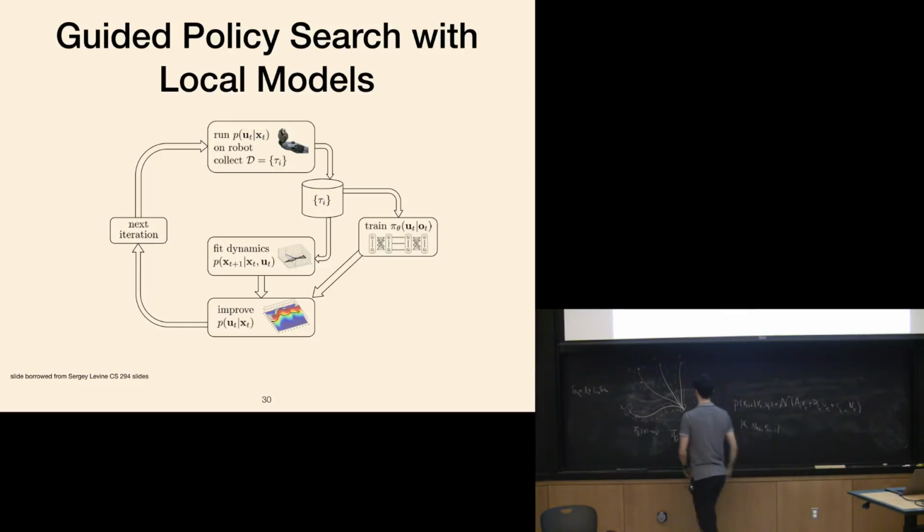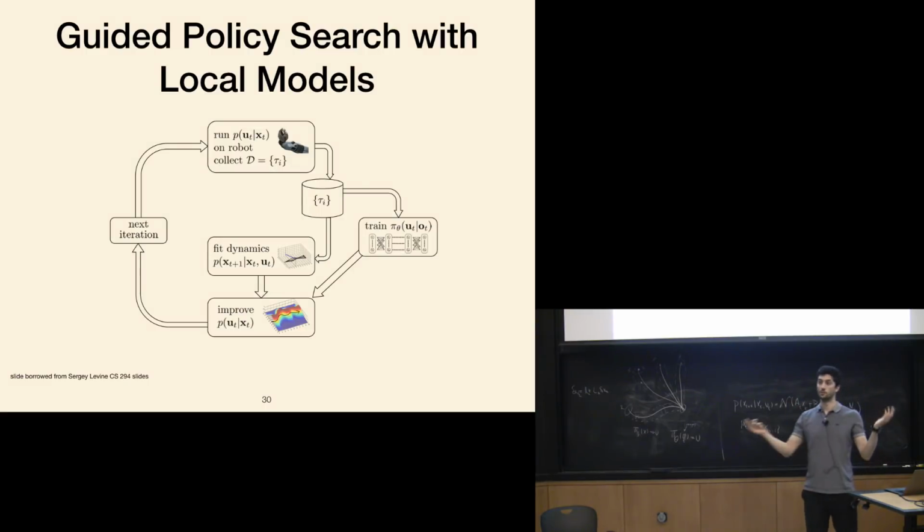Well, one thing you can do is, instead of having your learned policy take in state, how about we have it take in observation? Okay, so let's try to mimic a controller that was learned using state. These controllers very much use state. And let's try to just make it work just with observations. So they have a follow-on work where basically these are images. It also has the joint angles and stuff, but it doesn't have the target positions. So that's kind of how you convert these local policies into global policies. It's one way to do it.